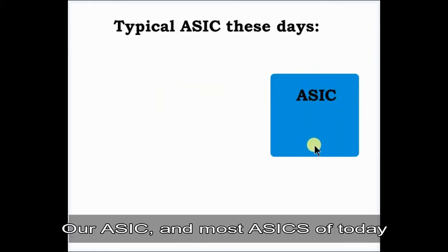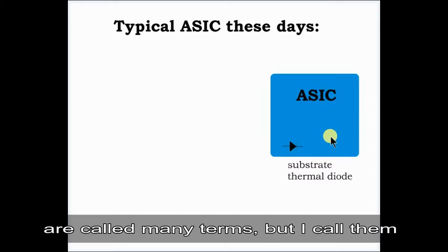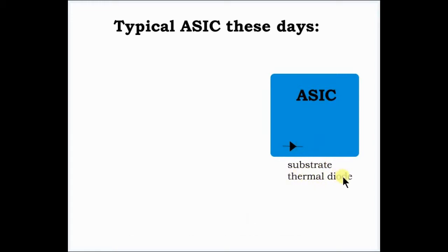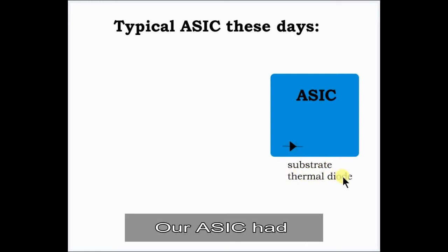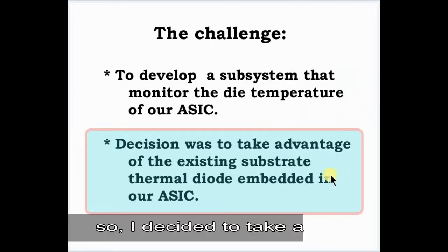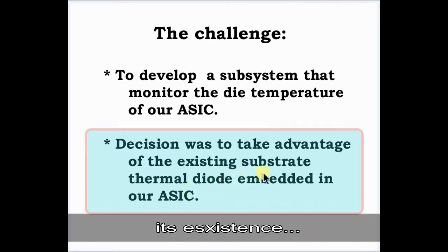Our ASIC and most ASICs of today have embedded diodes, and they are called many terms, but I call them substrate thermal diodes. Our ASIC had one of them, so I decided to take advantage of its existence.